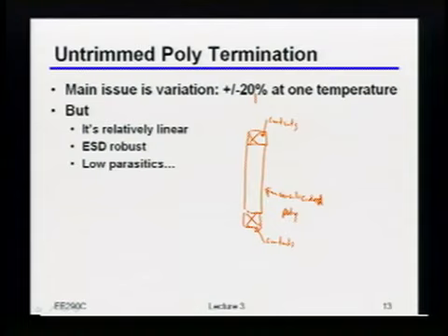I mean the transmission line. Oh, in the transmission line itself. Okay, that's a great question. It depends on the exact PCB, but it's generally quite a bit better than this, especially if you're not pushing the limits of what the process can actually do. Largely that's driven by the thickness variations, and those are reasonably good. I don't remember the exact numbers, but I think those are on the order of plus minus 5% or so. And in fact, if you specify to the PCB manufacturer, hey, this is a controlled impedance line, please be careful with it, you can probably do even better than that.